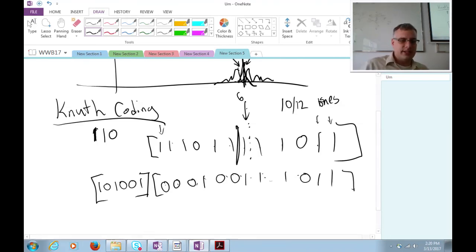I've balanced the bits. Both the preamble I added and then now the data sequence that I transmit itself are balanced. And I haven't increased the data rate very much. And so obviously the more complicated, this is a really nice algorithm to run when you're encoding thousands of bits at a time. Probably, maybe not as practical for backscatter systems. I don't know, you could analyze that technique.